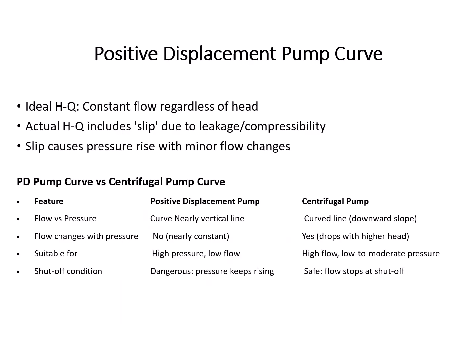Positive displacement pump curve. Positive displacement pumps are like bulldozers, you know. They push a fixed volume no matter what. Whatever amount of fluid, they will push it, no matter what its density or volume is. But in real life, a bit of slip happens, especially with compressible fluids or high pressures.